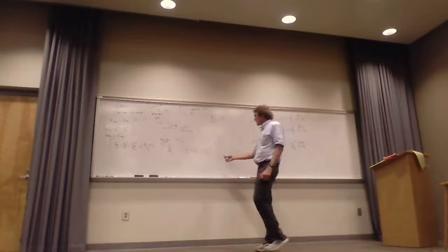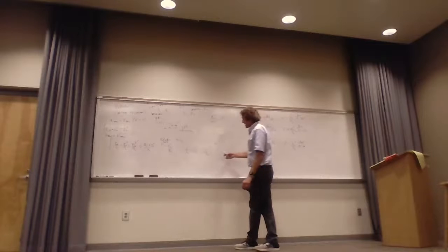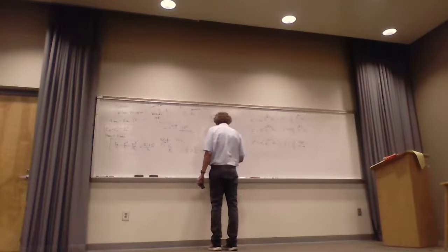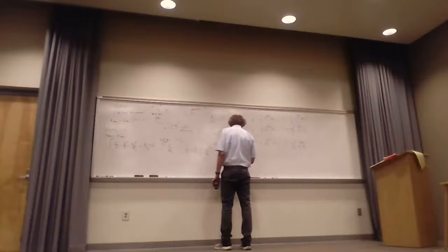Now y'all see, I can multiply both sides by eta 2 eta 1. Then I can organize things, but here's what I'm going to get. At the end, I'm going to get the reflection coefficient equal to eta 2, the impedance I'm going into, minus eta 1, the impedance I came from, over the impedance I'm going into plus the impedance I came from.